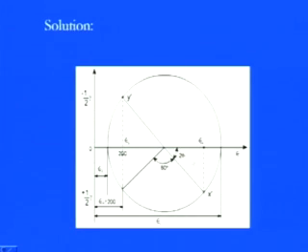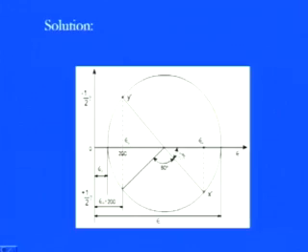So, now once you have the 2 theta 1, because this is the measured angle, that at what plane these strains are existing. So, now we have the angle 1, and then they were asking what will be the new strain components, the direct as well as the shear strain. Simply rotate 30 degrees to the clockwise direction from the x axis. Now since it is 30, we need to go with the 2 theta as we have discussed previously. So, a 60 degree angle you need to make. So, now you see here the 60 degree angle, draw this drop.